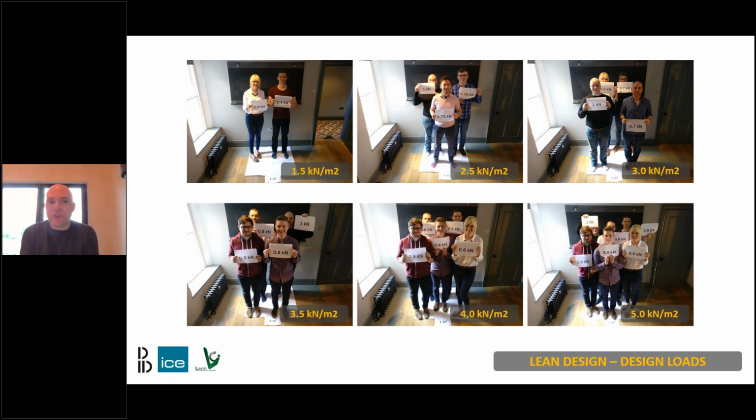But what's really interesting is that quite often, for instance in a commercial building, we're asked within the client's brief to design the floor plate for 5 kilonewtons a square meter. And you can imagine that within a commercial office space, how often would you cram that many people into 5 kilonewtons a square meter? So really it's about interrogating the brief, interrogating the design loads and saying, do you really want us to design that building for that magnitude of load? Because 2.5 kilonewtons a square meter would be more than adequate for a commercial office space, and actually for the future use of the building as well.